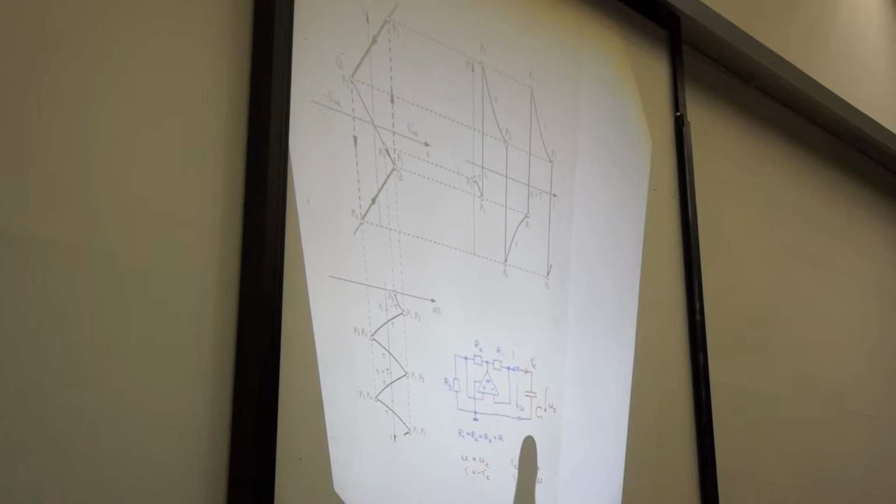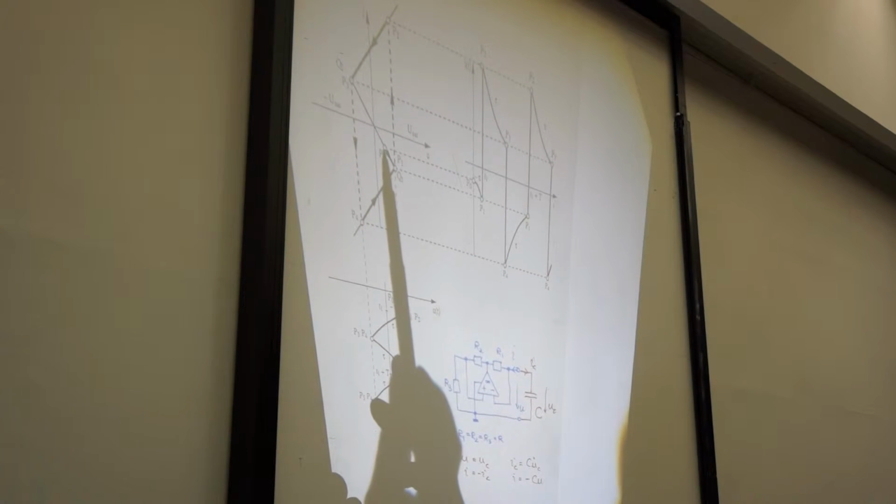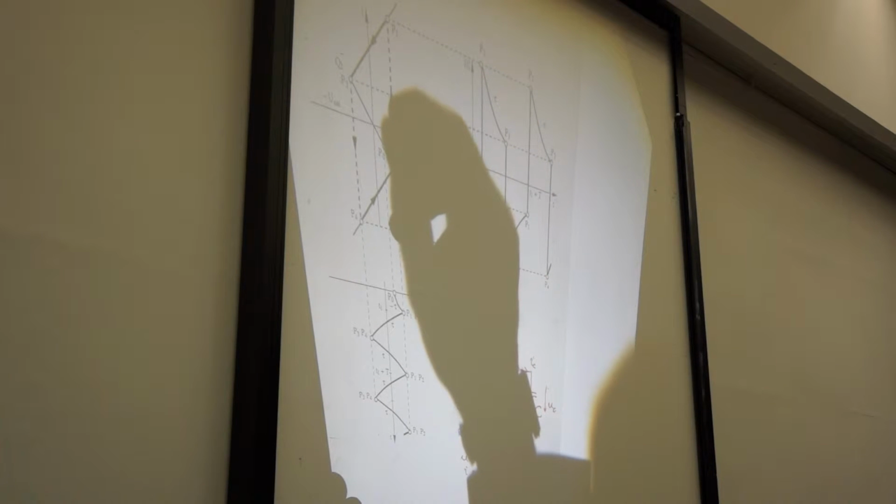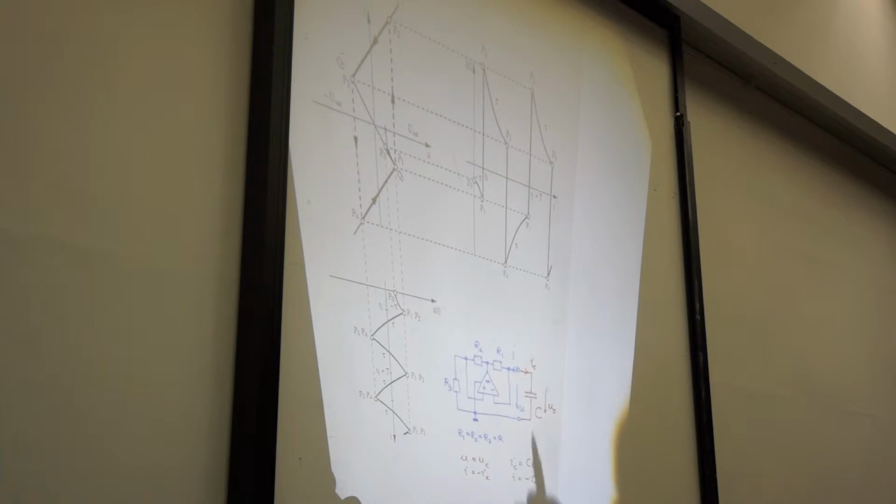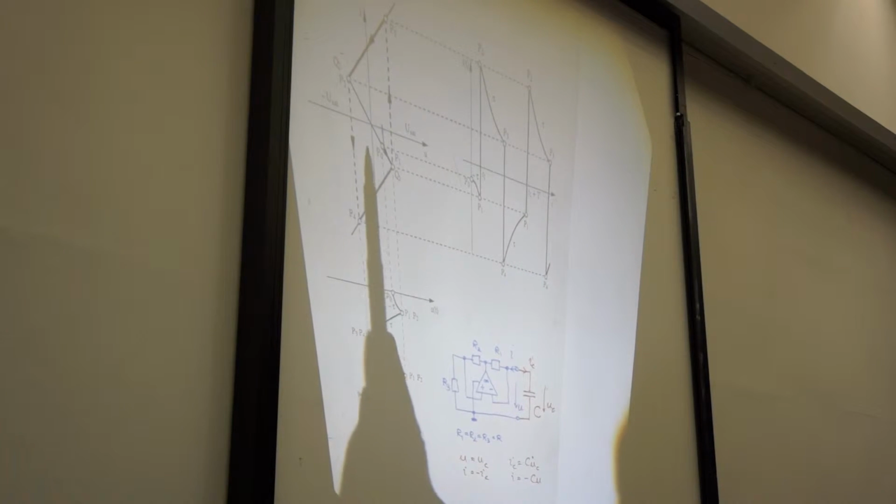And by connecting a capacitor across the terminals of this nonlinear one-port, we observe an interesting phenomenon which we call the jump phenomenon. So when we start out with an initial value of the capacitor voltage in this point P0 here, and look at the dynamic route in which direction the voltage will change, we observe that due to the negative current,